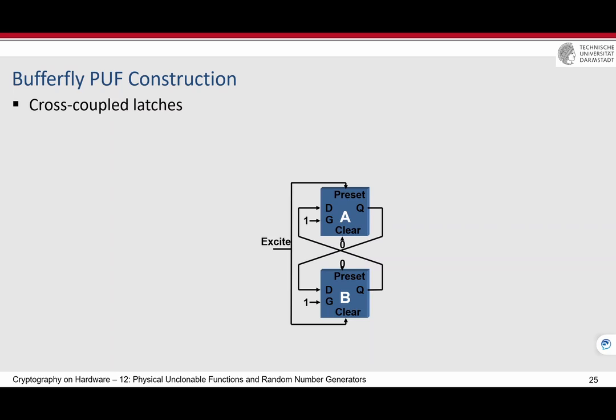If you remember, when you instantiate the block RAM, you give the init values, for example, what we use for the S-boxes of the AES, or for the T-table implementation. Then the initial value of the BRAM should be given. If you don't give it, then the synthesizer would fill it with 0. It means that after the power up, the value of the block RAMs is already deterministic, so you cannot use the block RAMs as the SRAM.